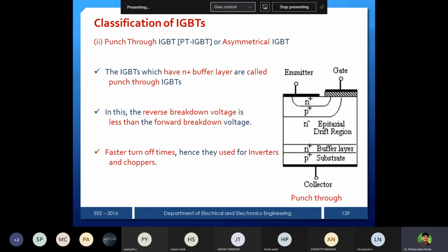Normally, the switching operation plays a major role in power electronic controllers. Why? Because for any controller you take, whether it is an inverter, a chopper, a cycloconverter or a rectifier, the operation is based on the switching operation. You operate the device in only two modes, on mode and off mode. Once you turn on the device for some duration, then you must turn it off.